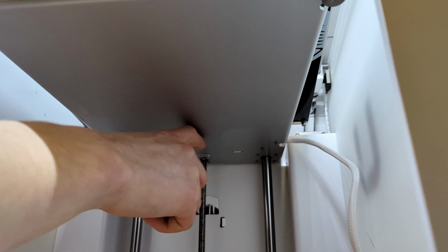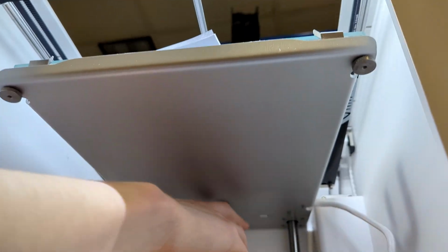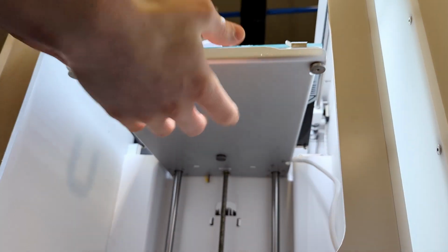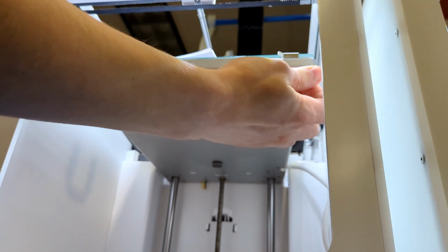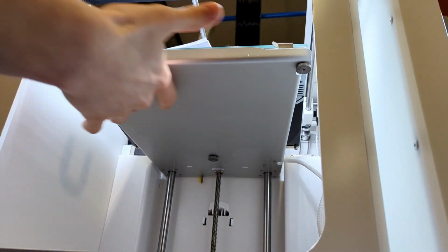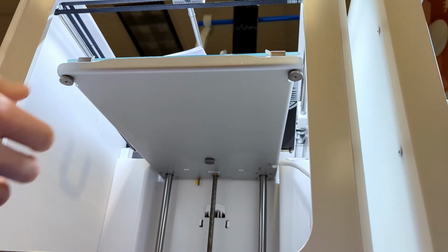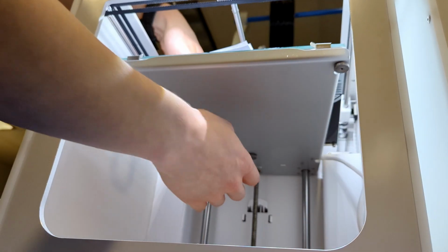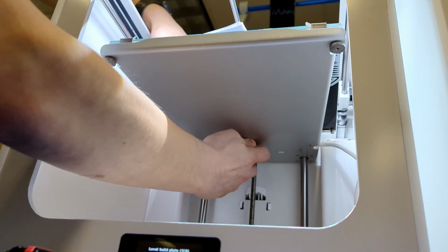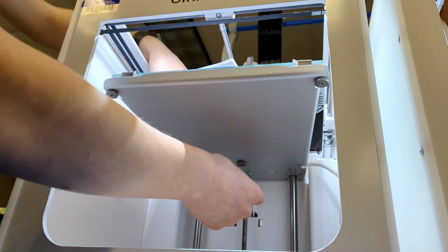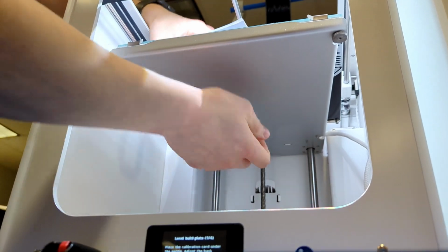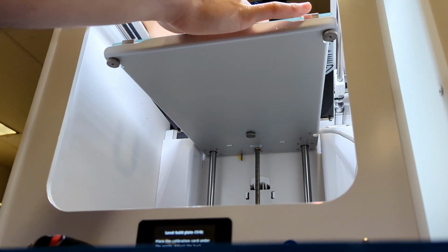So if you go on the bottom, there's a screw back here and a screw here and here. So there's 3 screws. It's like a triangle. That is all your adjustments. So it's a triangle for adjusting the level. It gives you a bit of options in all the axes. So basically you put the card under the nozzle and you're gonna tighten it. So righty tighty, lefty loosey. So you're tightening the screw, turning it right until this piece of paper will go under the nozzle.